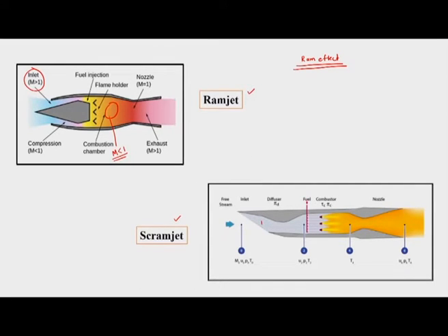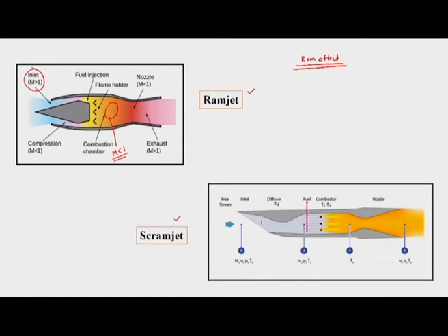In case of ramjet, we would first have some shocks, and those shocks, since the flow is greater than 1 Mach number, so it is a supersonic flow. So, we would have some shocks appearing, and then those shocks would give rise to the pressure after passing through the shock, and then we will have combustion. So, ramjet intake is designed to have a certain structure of the shock. We will define the efficiency of the intake, then we would come to know what kind of requirement we would have.